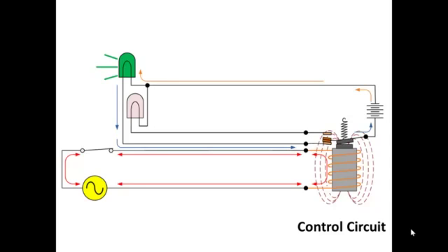So you could say that the contacts, the normally open, normally closed contacts, define the state of the relay. The normally closed contacts are true, or they conduct electricity when the relay is de-energized. So the normally closed contacts are true if the coil is off. The normally open contacts are true and conduct if the coil is energized. So normally closed are true if the relay is off. The normally open are true if the relay is on.